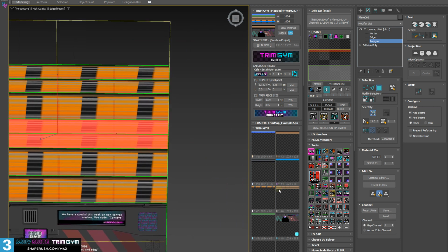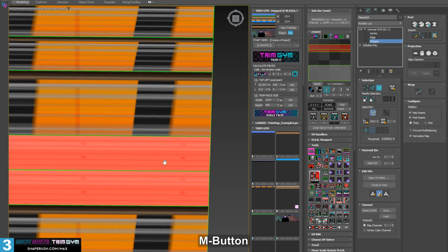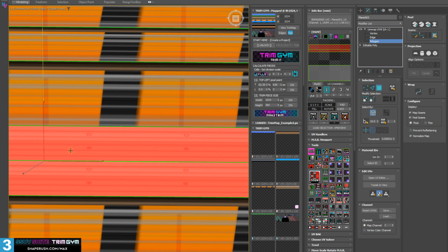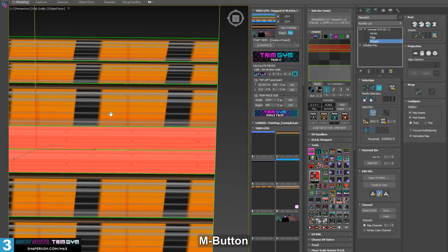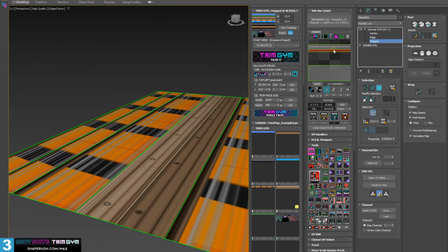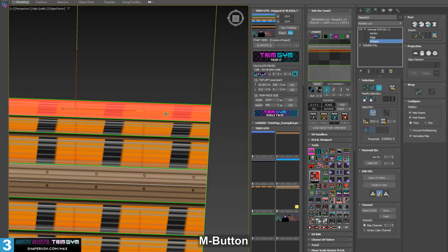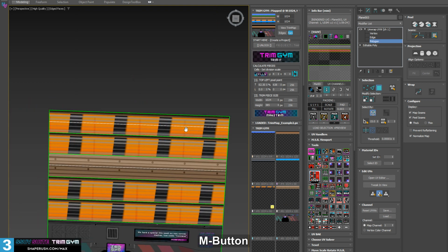I'm going to right click on this. What that's doing is moving those elements to those positions as they were currently standing. I need to explain this more in depth in a moment, but if I wanted to heal this and just make this into that bar, I can shift right click, and this will basically planar heal and map that to the coordinates that I have defined by that trim piece. Okay, so we can look at this again. We'll do that with the two orange pieces here, but I'll do it with the orange piece itself. Shift right click. There you are.